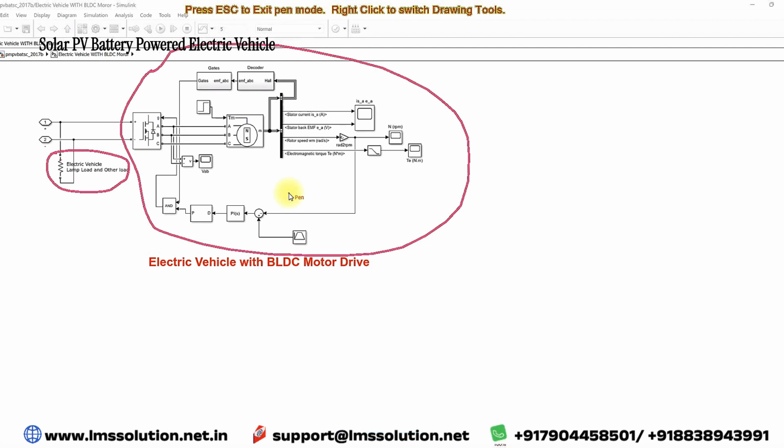It consists of a voltage source inverter and a BLDC motor, with closed loop speed control. Here you measure the actual speed of the BLDC motor, and it is compared with the drive cycle command and processed via a PI controller. The PI controller generates the duty cycle, which is processed via a PWM generator.